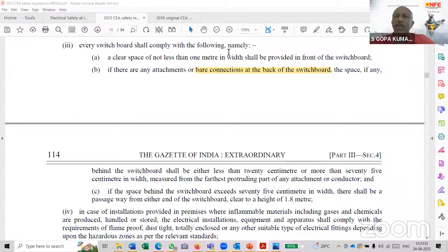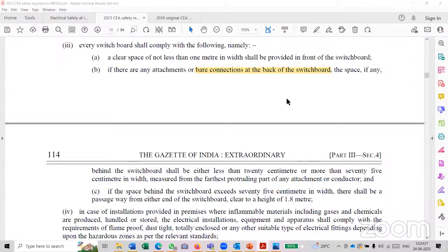So thanks to all of you for answering these questions. Now probably we can take up some of the questions from the question answers. But before that, I would like to add one small point. If we look at IS 732 Annexure A, let me open that one moment, please. Annexure A, provision for basic protection, various enclosures, is talking about the arm's reach. So basically this has come, I think, from the arm's reach point of view as a measure for basic protection, but the wording is not correct. The bare conductor wording could have been improved. Anyway, probably we can talk about it later.